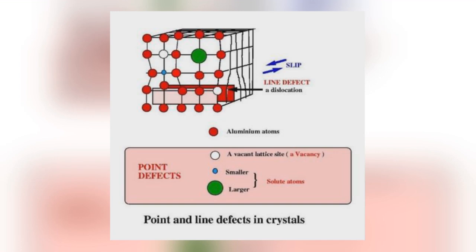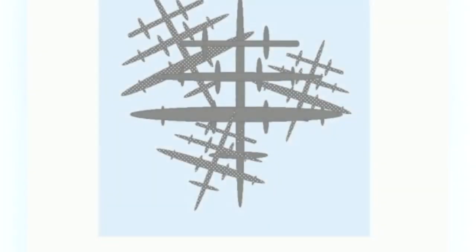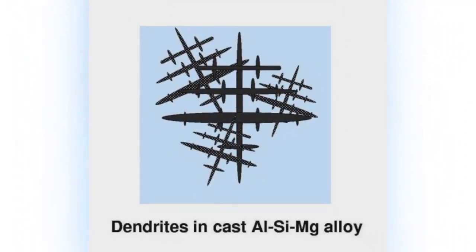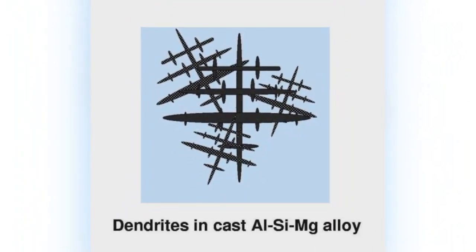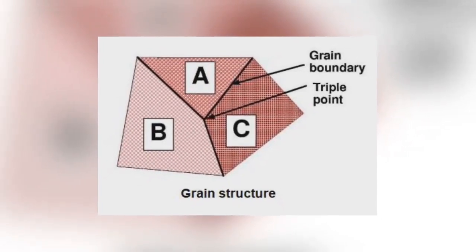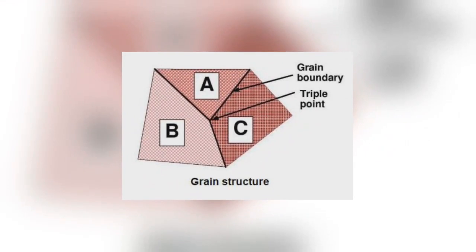As the liquid aluminium cools to, and then below, the freezing point, small crystals of solid start to grow within the liquid. The solid crystal grows at different rates in different lattice directions, and the crystal takes on a characteristic so-called dendritic morphology. Fully solid cast aluminium consists of colonies of dendrites with grain boundaries that have higher energy, leading to potential grain growth.